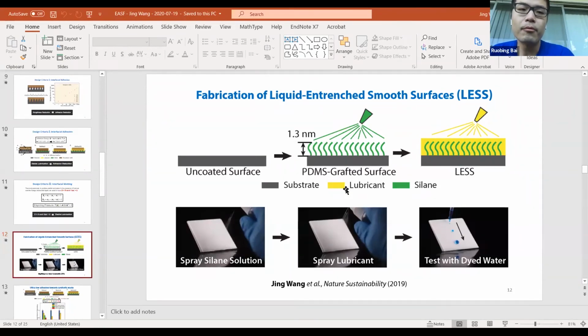But I think one scientifically interesting point is now if you have a silicon oxide bond, then especially with a lot of water, over time we know from glass this can have stress corrosion or crack propagation. So for PDMS, you can expect a similar thing.